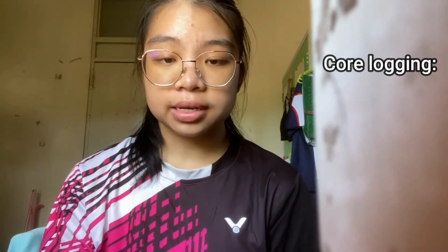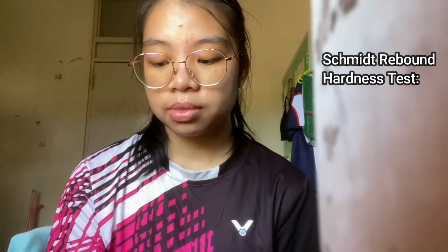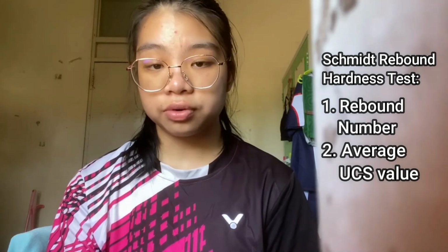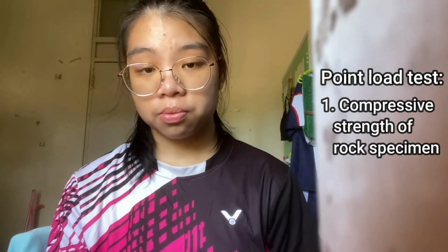From core logging, we obtain the RQD values and also know the description of rock. As for the Schmidt rebound hardness test, we obtain the average rebound value and also the average UCS value of the concrete. And as for the point load test, we obtain the compressive strength of rock specimens from the irregular lump test.